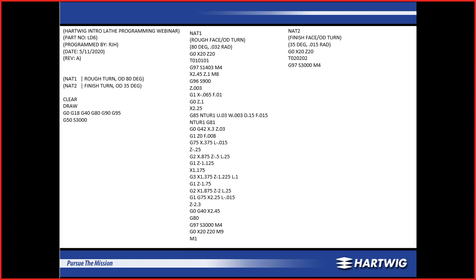Again, we're making sure the spindle is turned on and rapiding to a clearance point. This time I'm going to 100 thousandths away radially from my smallest diameter. Saves a lot of time so that I'm not facing air all the way down the part. Now I'm at double my 100 thousandths away in X positionally because again the machine programs in diameter. 100 thousandths off the end of the part and turn coolant on.